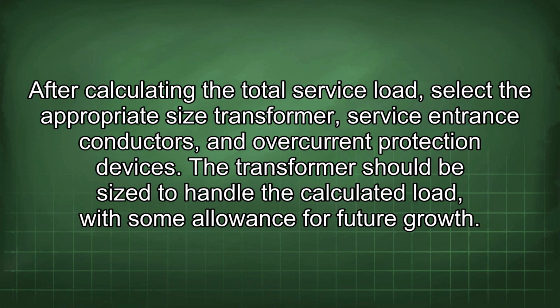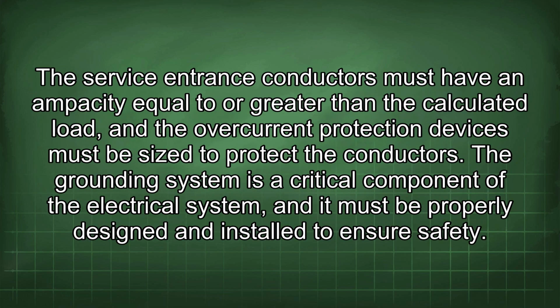The transformer should be sized to handle the calculated load, with some allowance for future growth. The service entrance conductors must have an ampacity equal to or greater than the calculated load, and the overcurrent protection devices must be sized to protect the conductors.